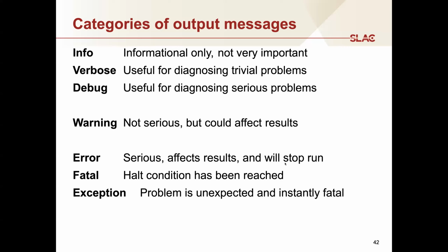It might not stop right away. It might take a few extra steps to unwind whatever it is doing, and so you might get multiple error messages in a row. My advice would be to pay attention mostly to the first error message, because that's probably the one that initiated the cascade of errors. The other errors might be helpful to help you see how it got to that final error, so you can see which part of the system was contributing to it. And oftentimes, warnings eventually lead to errors, and so looking at the warnings is quite useful when you see an error.